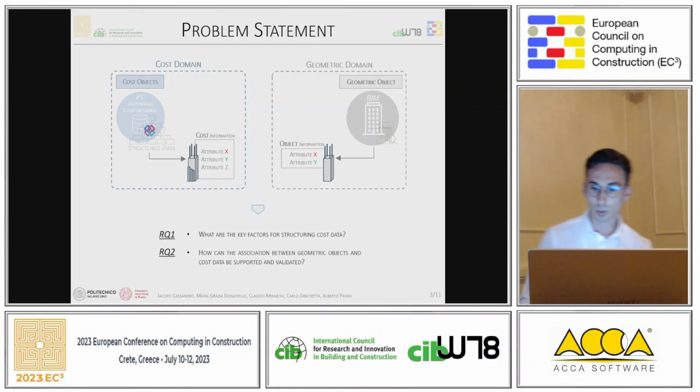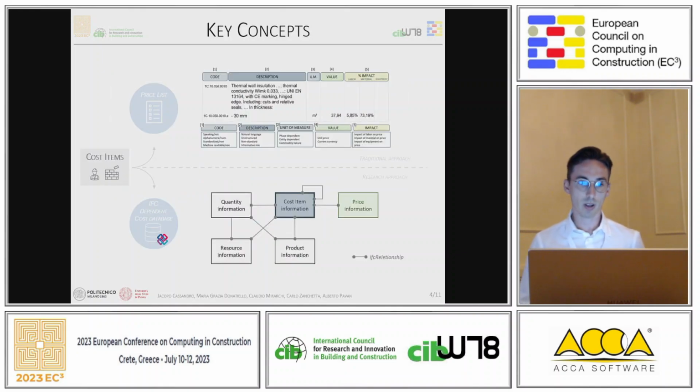Yeah. These are the two research questions that come from this problem statement, and to support, verify and improve the quality of cost estimates in public tendering, the study proposed both the identification of a structure for a cost database on IFC and the reliability and application of these methods. And this will make it possible to identify a standardized procedure for storing, exchanging, and linking the cost information to the model objects. To this end, an approach was adopted to consider the cost element as a structured class in the IFC data model, known as IfcCostItem, and this entity contains a set of attributes in which information can be instantiated and a cost ontology based on structured classes can be identified.